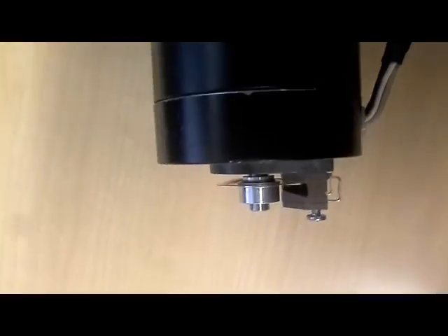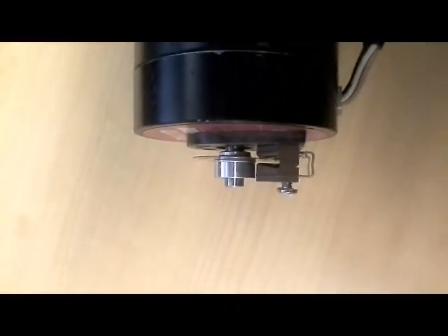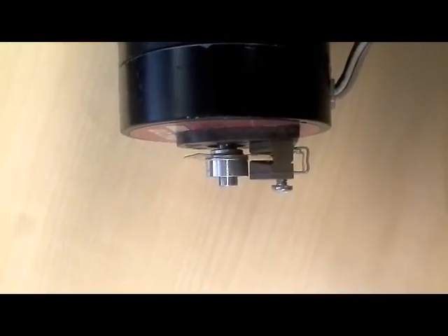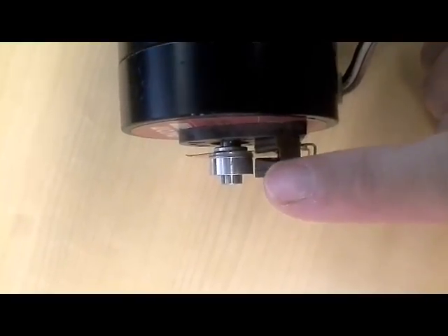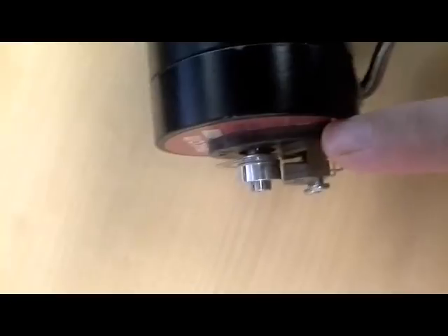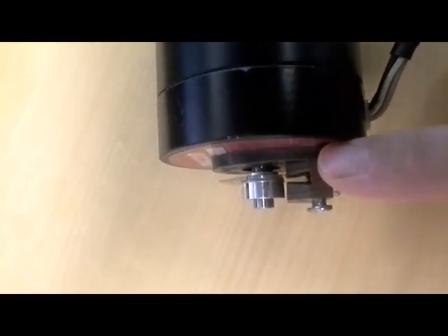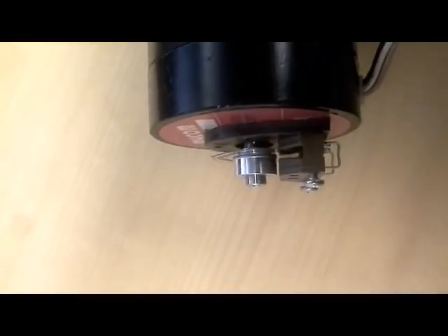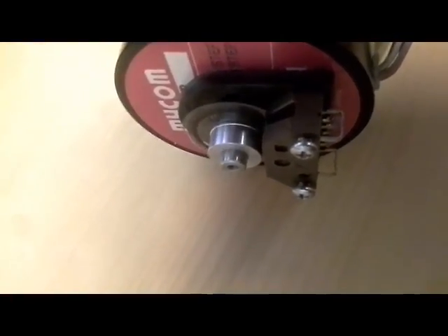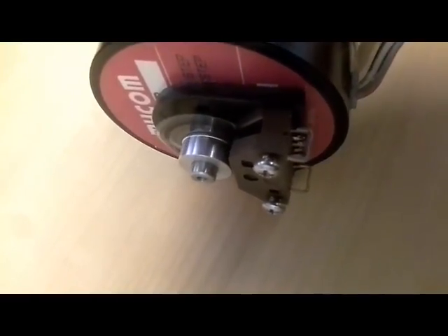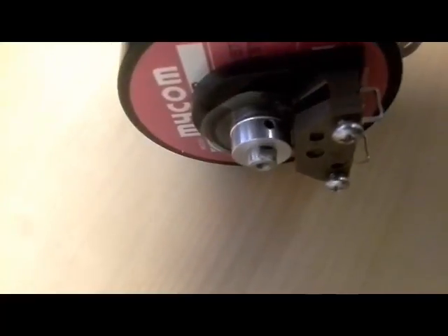Now, the plastic disc is positioned so that it is right in between these two brown plastic parts, which you can see right there, a top and a bottom part of this plastic. Now, in the bottom part of this plastic, there is an LED pointing up so that it shines through the clear plastic disc that rotates with the shaft. As I rotate the shaft and the clear plastic disc rotates, these little lines that are in the disc alternate.